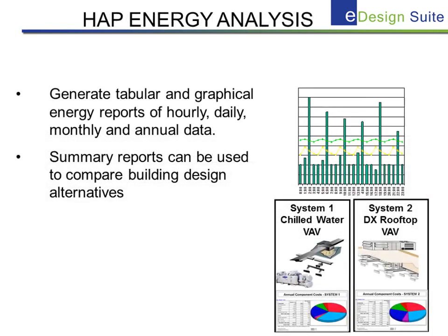For energy analysis, HAP can perform schematic design, rapid energy modeling, results involving simple skin-deep type inputs. To do this, it uses intelligent defaulting to generate fully detailed models automatically. For detailed design, also called design optimization, HAP will model detailed HVAC system configuration, controls, and performance.